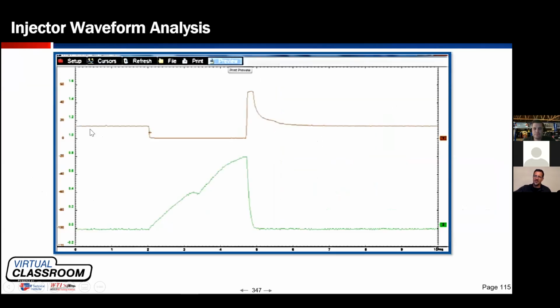So what we see here is the voltage supplied to the injector. The injector is controlled on the ground side on this vehicle. It could be controlled on the voltage side, like some older Ford trucks I've seen, like a Ford Ranger. What's that turbocharged one? I can't remember that engine. But here we can see this is 0 volts. It pulls darn near 0 volts, meaning all the voltage was used up on the injector side. And the fact that we have about 1 amp of current flow, maybe 900 milliamps, tells me we don't have a circuit problem. The fact that I see a pintle bump here tells me the solenoid mechanically moved, it shuttled. And the fact that our fuel trim is not elevated significantly tells me fuel sprayed.